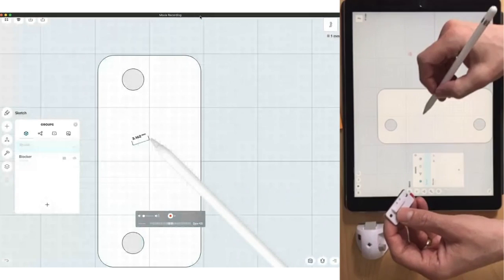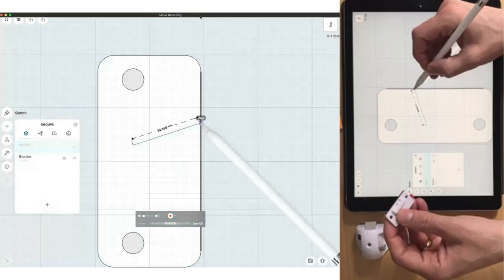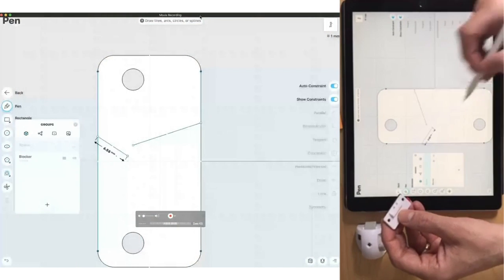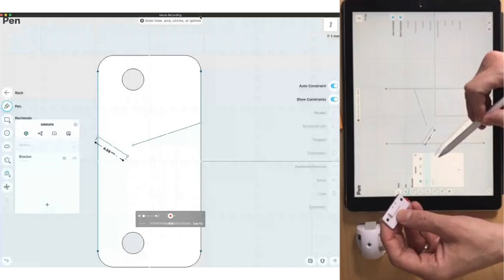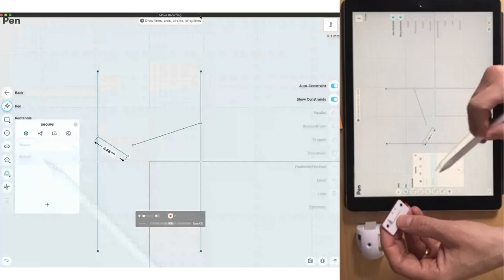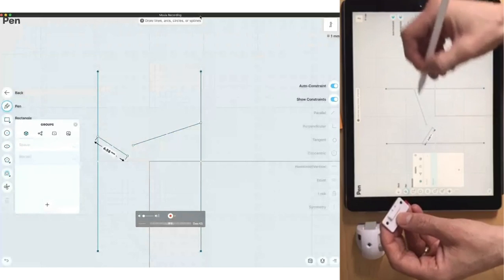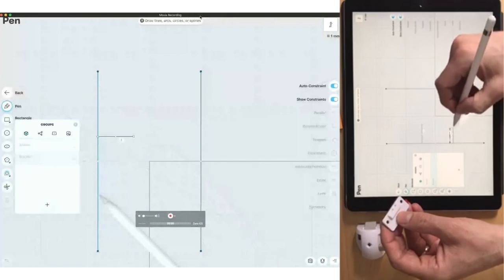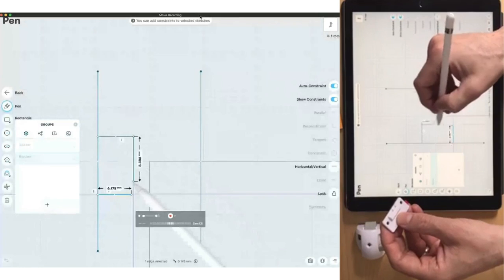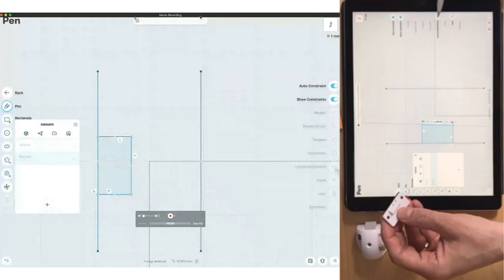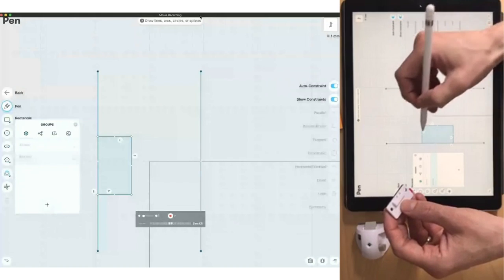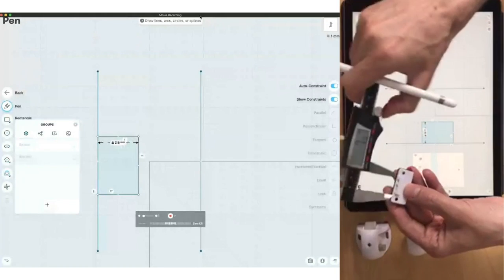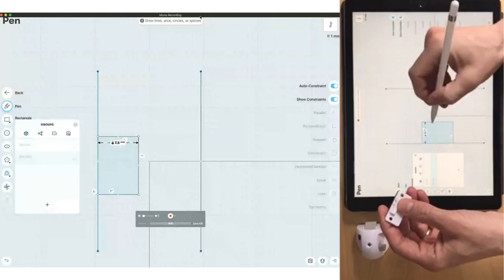this face. So I will start drawing a line, touch actually this edge. You will see that this then projects in the lines. You see, really nice. This line I don't need anymore. This one will make horizontal. This is okay, perpendicular there, horizontal, and then we set this is 7.5 and let's say 20.